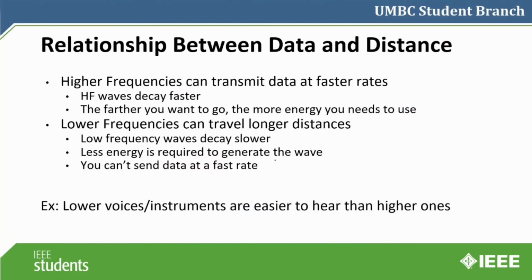And as I said before, high frequency waves will decay faster and it needs more energy to go the same distance. Low frequency waves will decay slower, but you can't send data as fast because you need to oscillate a certain number of times in each symbol.